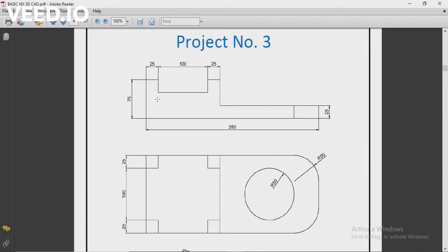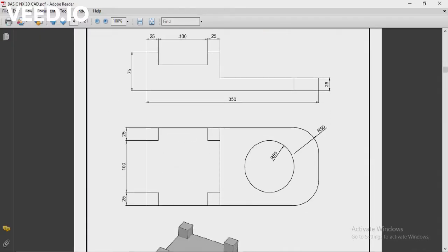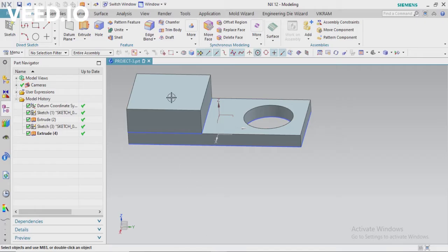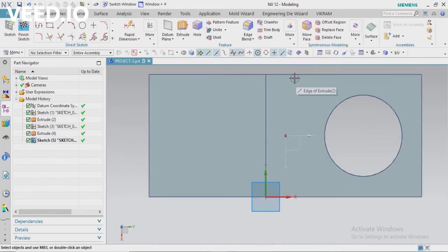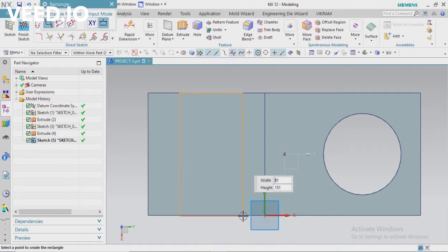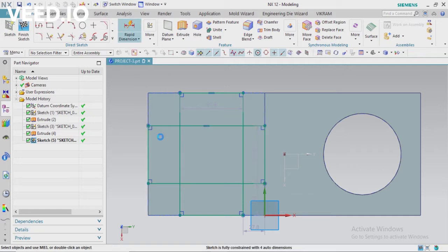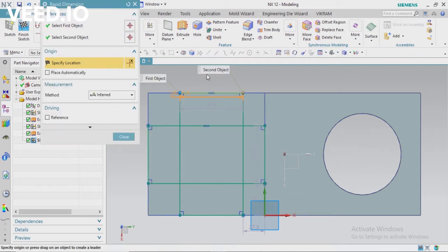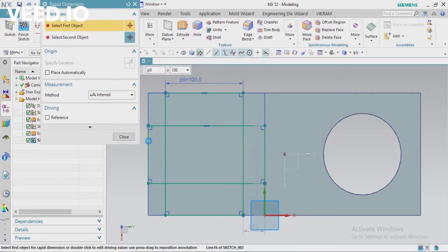Next step, what you are going to do, you are going to cut out some section. Okay, so first you create the middle section, the middle rectangle. So a cross middle rectangle I'm going to create. Just to create two rectangles, a corner rectangle, I think is the better option, and again horizontally create a corner rectangle, and you have to make symmetry, or you have to define boundary dimensions. Okay, so whatever values are required, you have to define all those values.